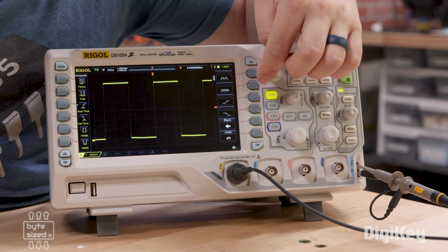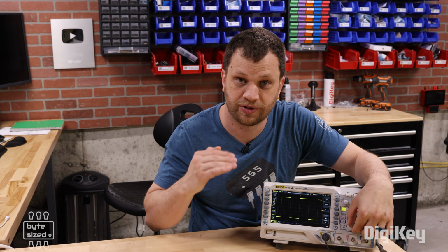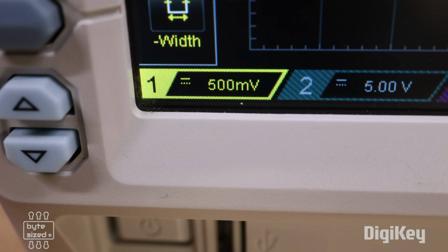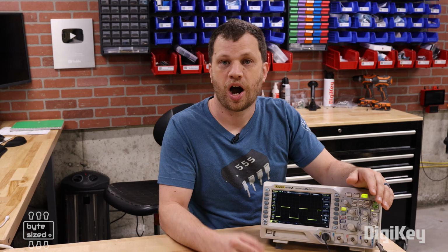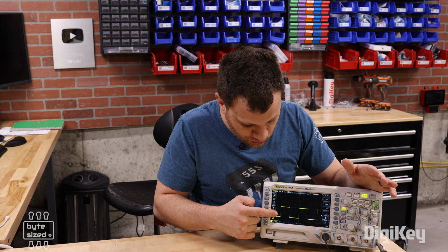On this scope, all of the vertical controls are outlined here in this area, and I can adjust the vertical resolution by turning this knob, and you'll see this number change down here. So now it is 1 volt per division. Our 1 kilohertz signal hasn't changed. It's still 3 volts, but our resolution has changed.